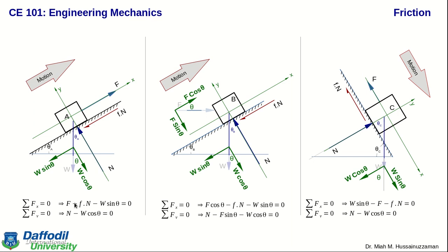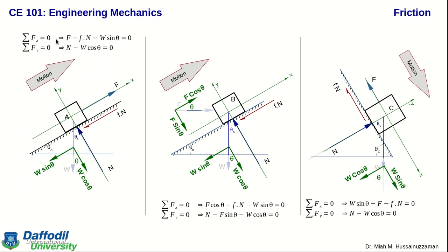So before that, I am removing this equation here. I am keeping this equation here, and I will derive new equations for the new axes. So I am now rotating the axes and placing the axes here. So this is horizontal and vertical. Now you can see this force is already along the new axis. We don't need these components anymore.